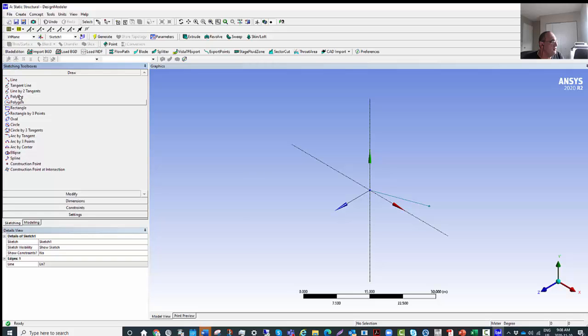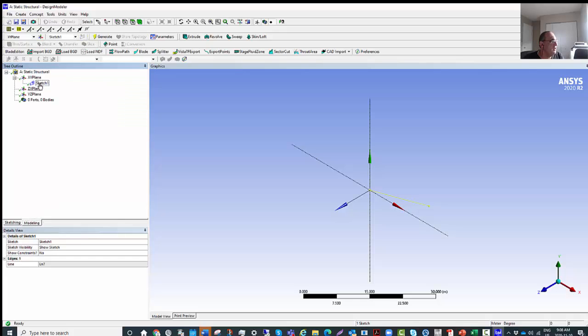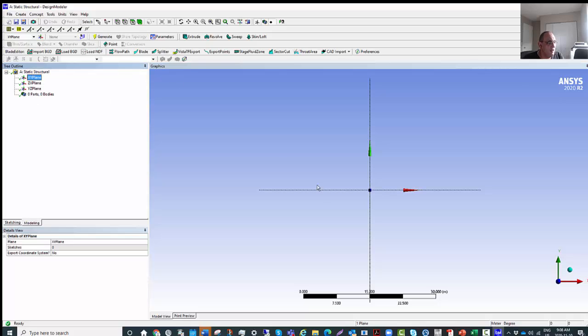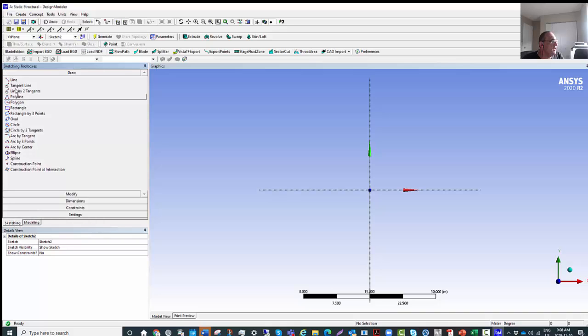Actually, I didn't prepare this beforehand, so I can show you some of the things that we can do. Modeling. So you can go simply here and delete this. Okay. So let me go here, Z plane, and then you can directly draw, or you can add a new sketch. So I'll find it as sketch 2. Okay, sketch, and I'm going to use lines,